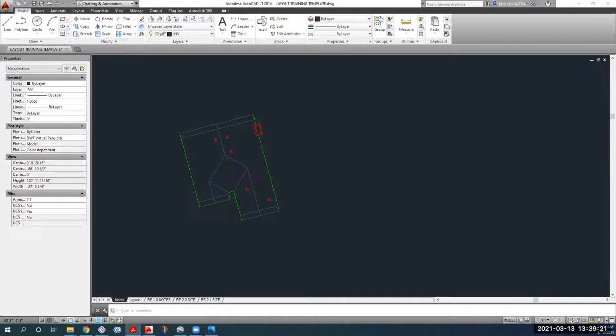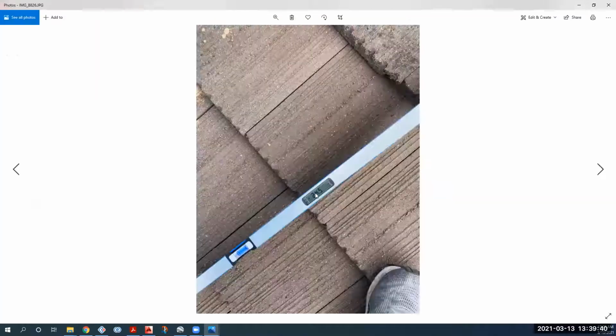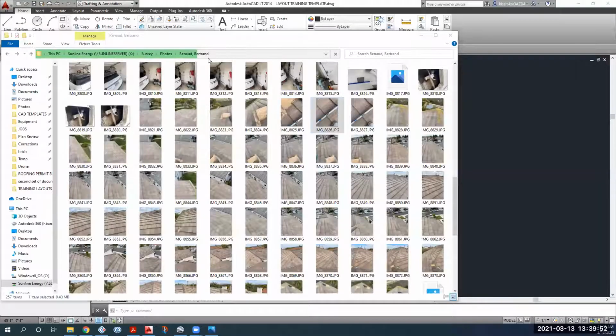If it's not on the survey, it's there in the roof measurements we actually do. One sec. Okay, so see, these are the customer's roof measurements, and one of our surveyors goes on top of the roof and puts this scale. So it's like 24.5. We'll round this down to 24 degrees, because we want to be conservative, and cosine of smaller angles is larger. So rounding it down means being conservative. Okay.